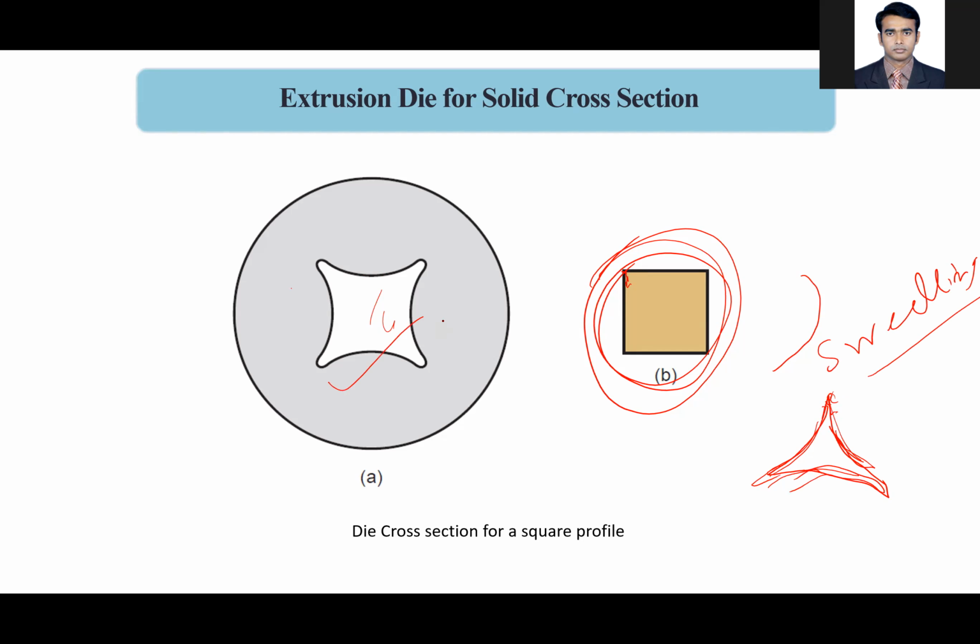So this profile is determined by a kind of trial and error, and extensive calculation is actually required, or nowadays numerical analysis is available. So you can also do some research on this, numerical analysis of the plastic swelling, and how the parameters change due to that. It depends not only on the pressure but also on the die outlet temperature, or the cooling method applied. So there are many other parameters, so it's a good research field.